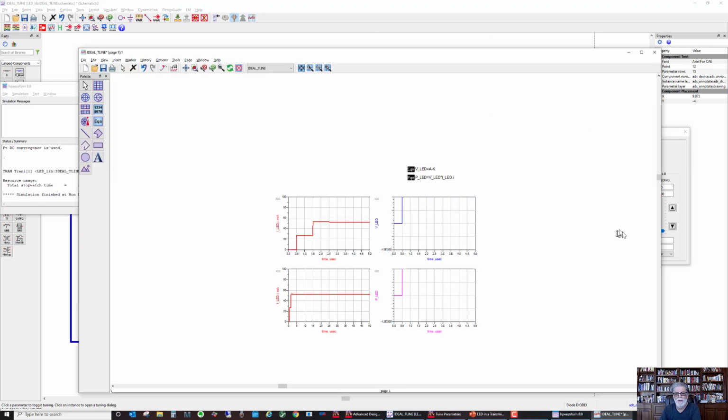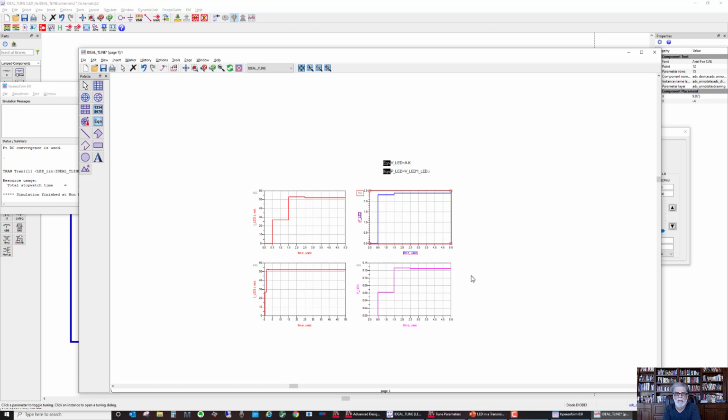Okay, and now you can see here is the current, and we can see the two different scales. We can also see the LED, and here I'm monitoring the LED current and the LED power, and you'll see that at a half a microsecond, the LED power goes up to 50 milliwatts. It's not the maximum. It actually hits a little bit more than, maybe about 130 milliamps, and you can see the one reflection in it. Eventually, it'll settle out at a little over 100 milliamps, and that is due to the 50 ohm resistor. Anyway, you can see the reflections.